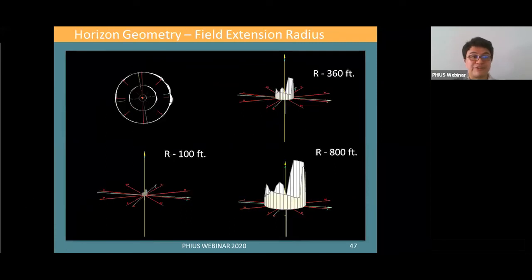For the horizon geometry method, we also have three cases with the same radiuses. To generate our geometry, we use the dual Pathfinder protocol, and we track shading angles from our sky dome images taken at the site. Also, through the calculator, we can scale up the horizon components and have similar cases as the 3D volumes.